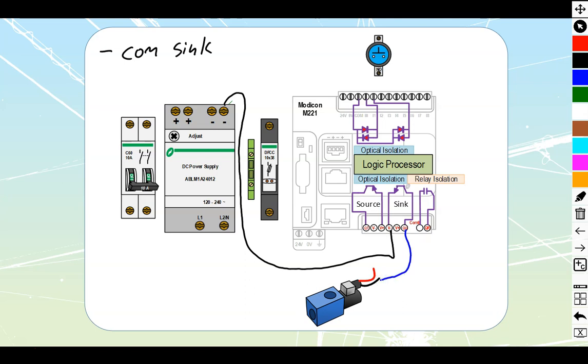We would carry that out over there to my negative terminal over here. And then this over here is going to carry the rest of the way back through. We've got a complete path for current flow. Once again, if we take a look from the positive through the fuse holder protection, we're going to go through my load itself, through the actual PLC, through that transistor that gets fired by the internal logic circuitry, all the way back to my supply over here. Fantastic. This is exactly what we are looking for off of these ones.